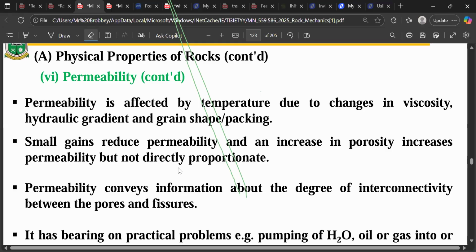Now, like the instance I gave when I started, there is a rock which is highly porous, called pumice, and there's another one called scoria. Those are tuff rocks, which means they are formed by volcanic ashes, and they are very, very porous. Those rocks having a lot of spaces doesn't mean that they are highly permeable.